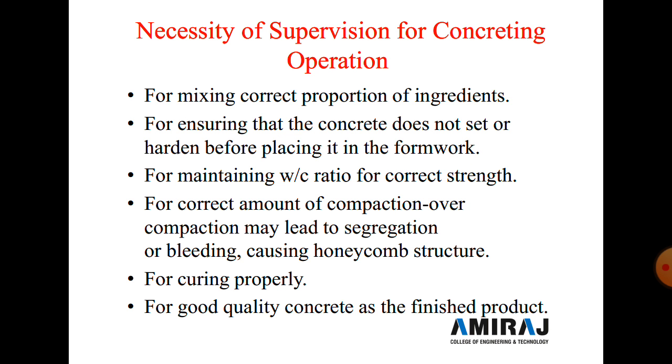Next is for the correct amount of compaction. Over compaction may lead to segregation or bleeding, and causes honeycombing structure. Next is for curing properly, and for good quality concrete as a finished product.